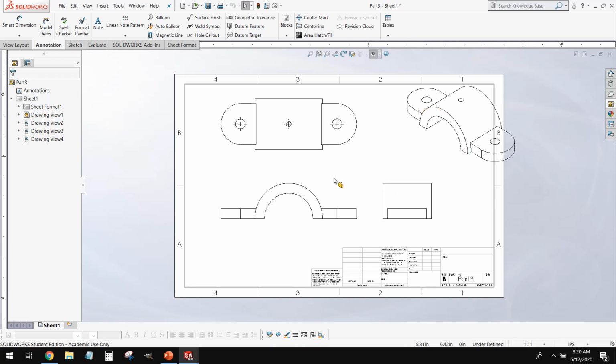Now this looks a little overcrowded right now, but that's fine. We're going to alter this so that it looks good. So, 1:1 scale. Now, you noticed our ISO view also blew up at the same time. That's because all these views are linked together. Our ISO view, since it's just for reference, we don't need it to be that big.